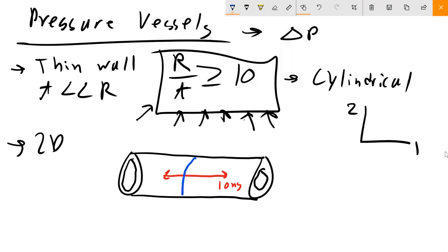And that's going to kind of stretch this. It isn't a great description, but it's like stretching the skin around the hot dog. So it's stretching the skin. It's not going through the thickness of your material. It is stretching around there. So the pressure is basically causing that material to stretch circumferentially. Circumferential, or most often hoop.